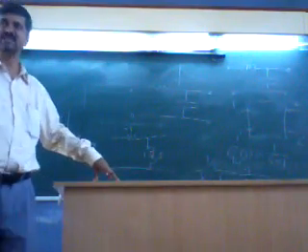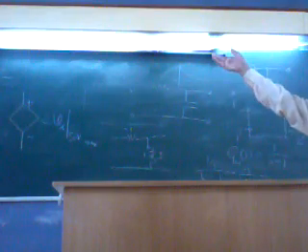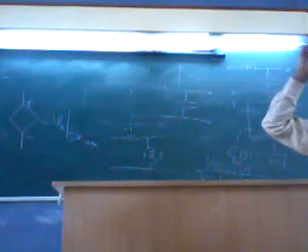And the moment it reaches that state, it no longer remains a dependent source, because Vx may be 30, but the output is 50. So the very concept of our linear network fails, and the system becomes non-linear up to some limiting state. So unbounded output never actually occurs. You should not be afraid that in practice it may happen.